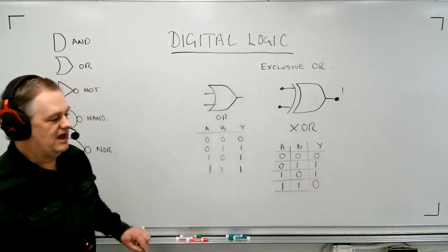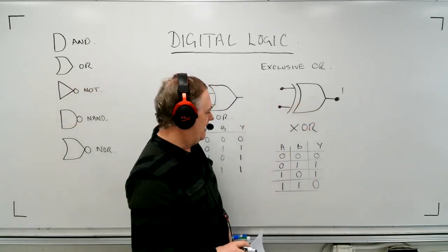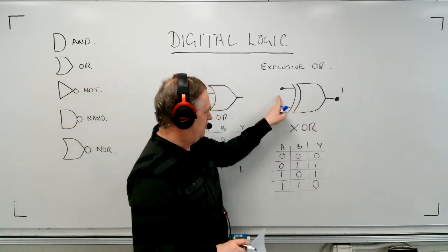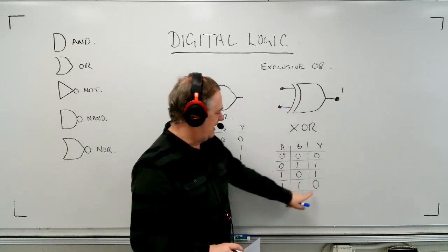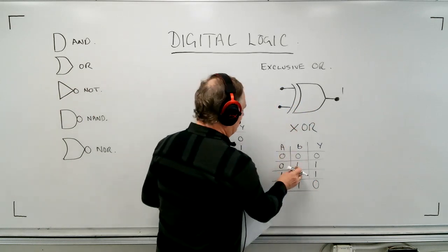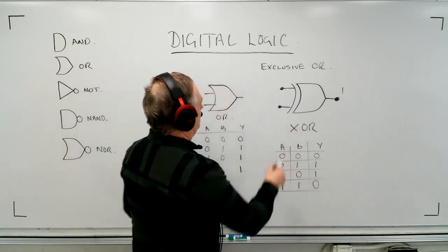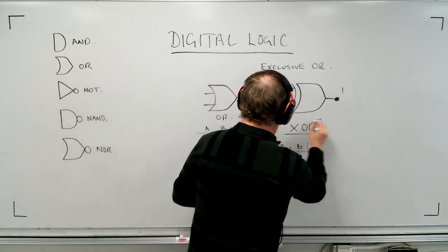And so you can see now that with this gate, I can definitely differentiate between whether I have only one signal input at a time, and if I have both on here, then it's actually going to be a low output. So it's a way of saying it's exclusively one or the other one. So the exclusive OR, and its name, of course, the XOR, okay?